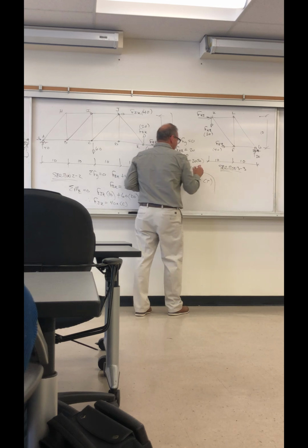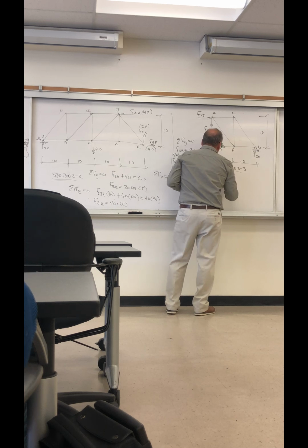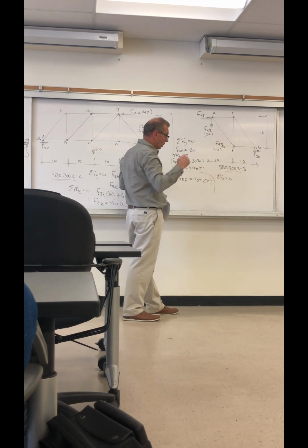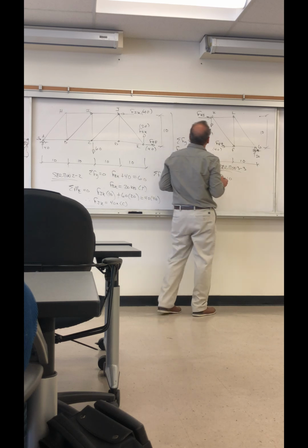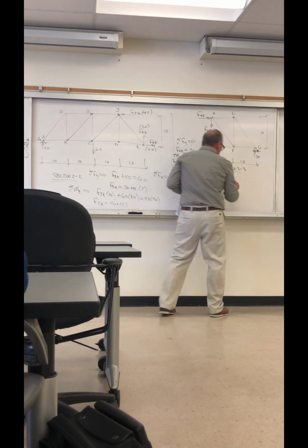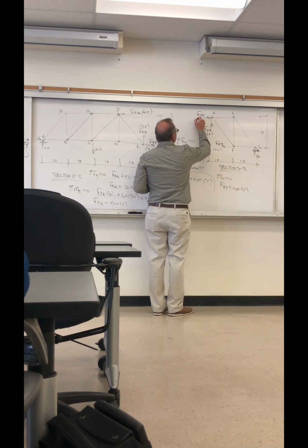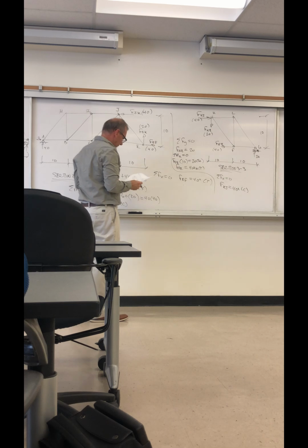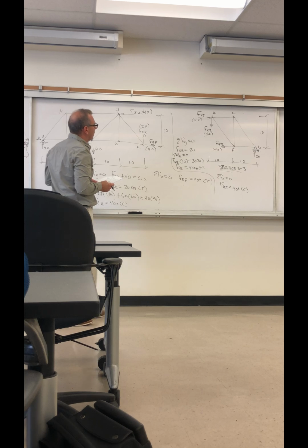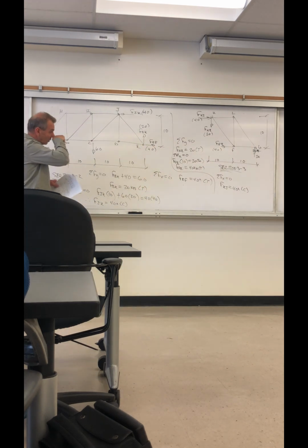And that's tension. And then summing forces in the x direction, you can see, again, there's no horizontal load here. There can't be, it's a roller. And there are no horizontal loads applied within this part of the truss or anywhere actually. So we get F of KJ must also be equal to 40, but in the opposite direction. That's compression. And the F of KE is 20. This is tension. That's sections 1, 2, and 3.